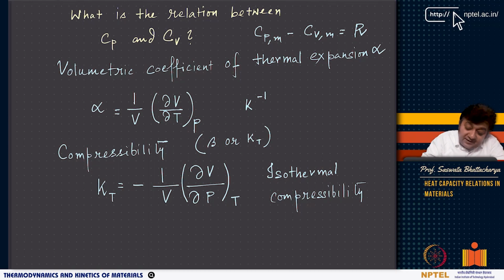So we are basically finding out different measurable quantities. Thermodynamics in general deals with macroscopic quantities, not molecular level quantities, and the macroscopic quantities that are measurable are more and more useful, because there will be quantities such as energy, for example, which is not directly measurable, right? But you can measure pressure, you can measure temperature using a thermometer, you can use calorimeters to measure heat capacities, whether at constant pressure or at constant volume. Also you can measure the coefficient of thermal expansion and the coefficient of compressibility.